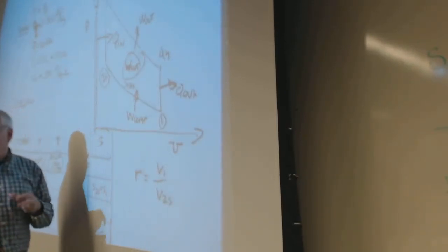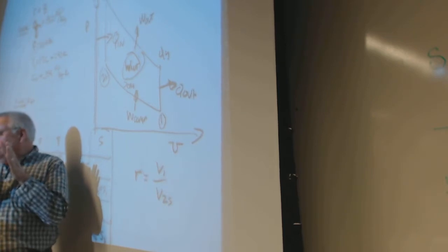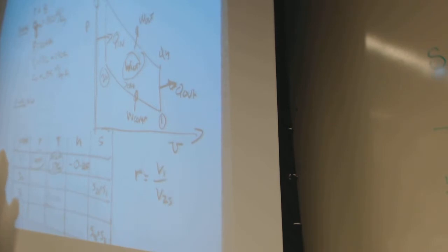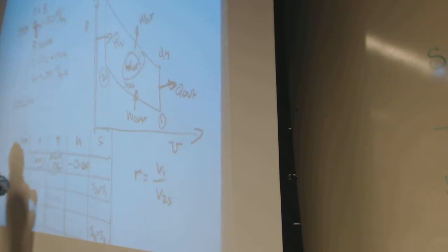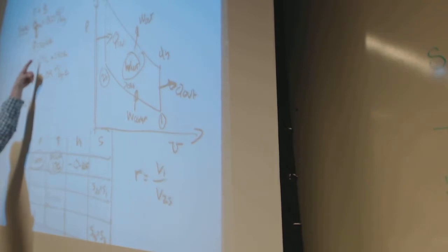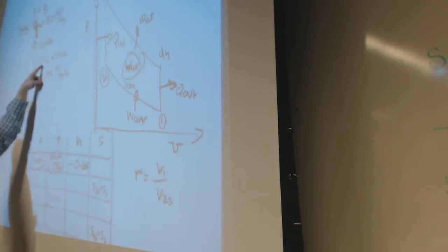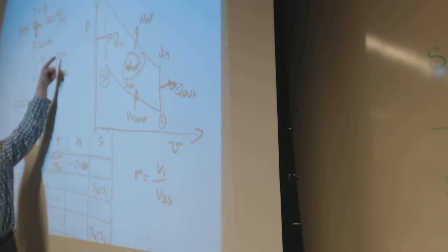But by golly, if you have some air and you only give it 1/8 the space that it had, it's going to have higher pressure and higher temperature. Ideal gas law says so. Put in that much energy, compression ratio of 8, came in at 100 kilopascals, which is atmospheric, 17 degrees C, which, with the ideal gas law, we need to be using absolute temperatures and pressures.